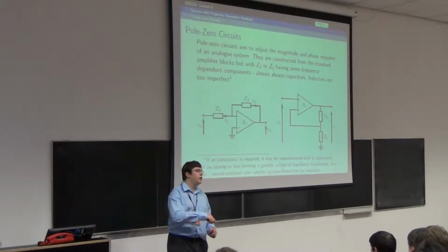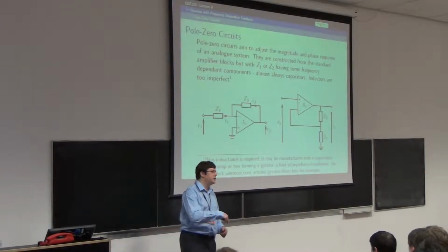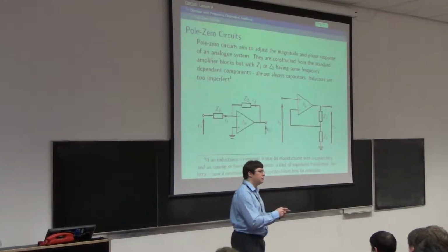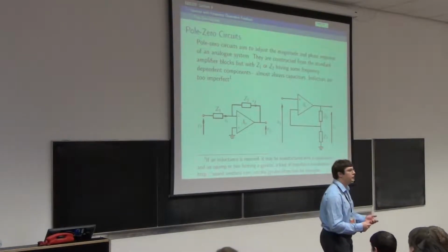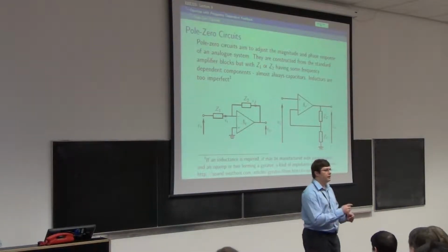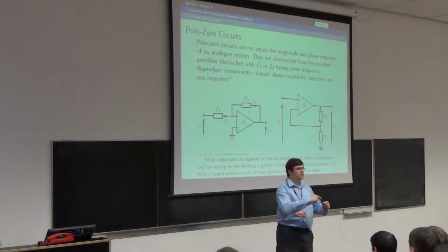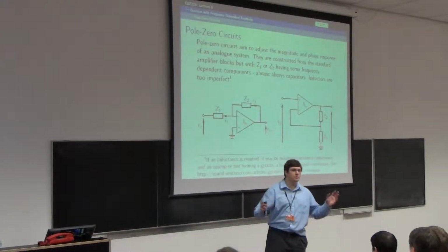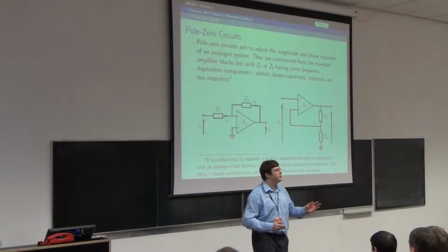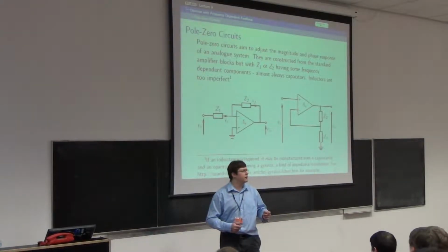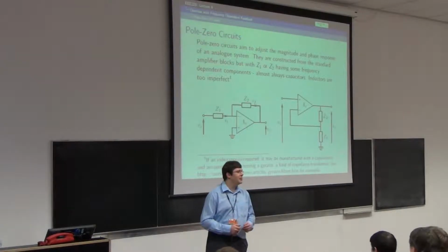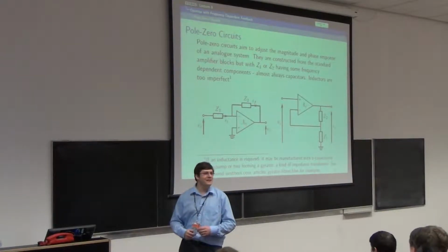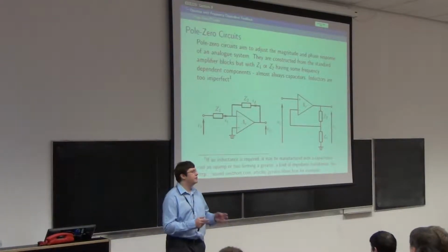Also, inductors, when you wind them, you wind the turns next to each other, and there's a bit of capacitance between each winding because the windings are insulated with enamel, it's like nail varnish. So you have L and R in series with lots of little capacitors all the way down in some sort of transmission line type structure. And having done the transmission line now, you've done it, right? Must have done, week 12. They're a bit messy at times, which is being nice about it. And you try to avoid any imperfections if you can.